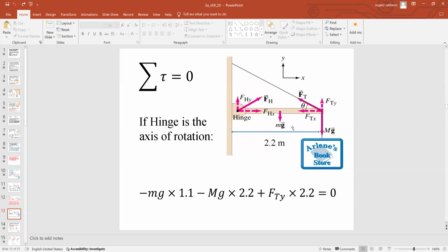expression. Second force is the load, the gravity from the load, the bookstore sign, pulling it down. And this is the line of action for the force. And that's the axis of rotation. The shortest distance between the hinge and the line of action becomes 2.2. So 2.2 meters.